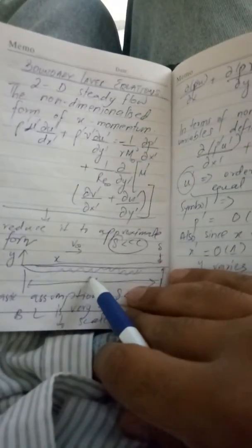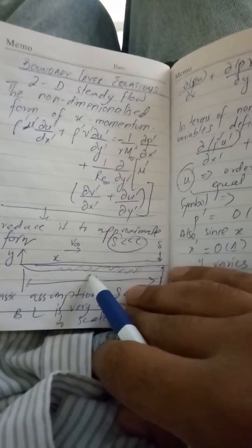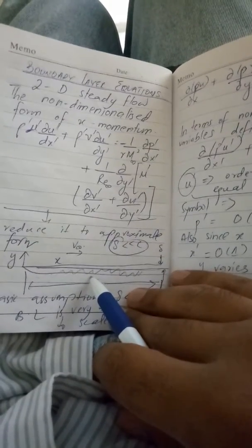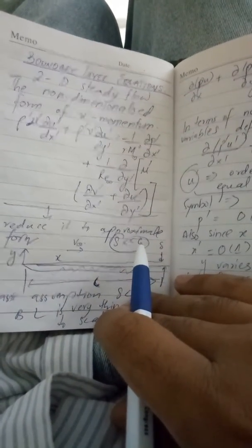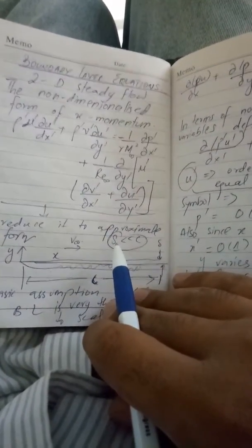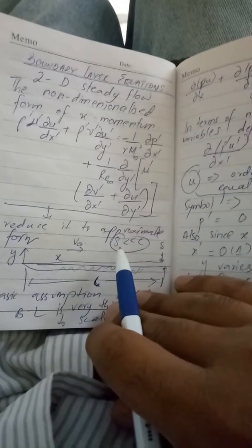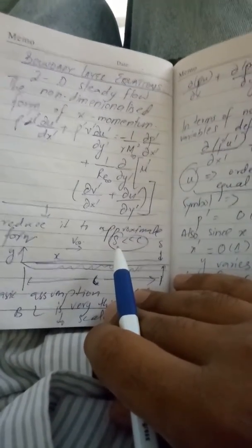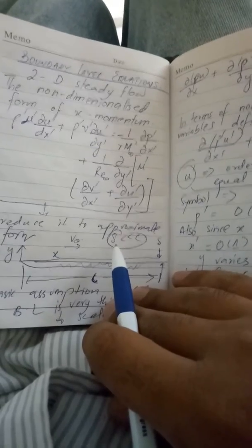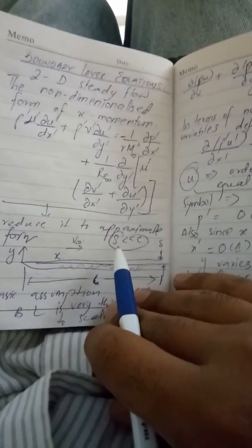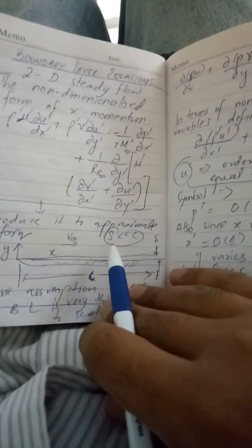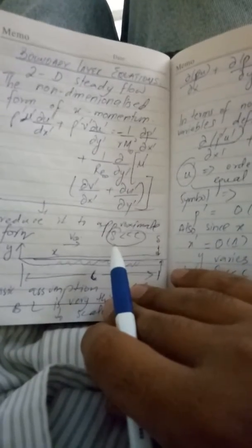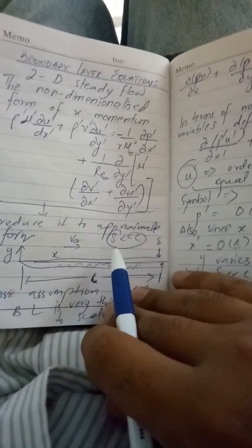We have taken the assumption that lambda, which is the boundary layer, is very small as compared to the scale of the body. Understandable. We have taken lambda in terms of y, and when we talk about y, we have talked about v as well. When we talk about x, that is the x-axis, we have talked about u, which is the velocity. Just multiplying rho, the density, into velocity, we get the momentum. We have talked about the x momentum. We talked about the y momentum by taking out the first order derivative.